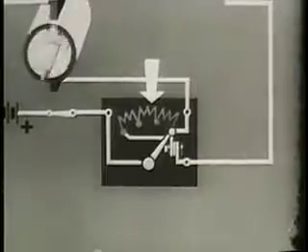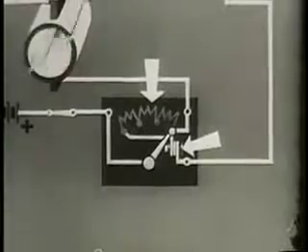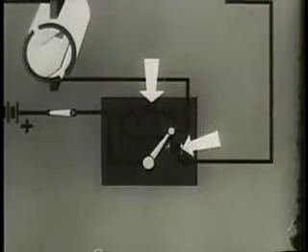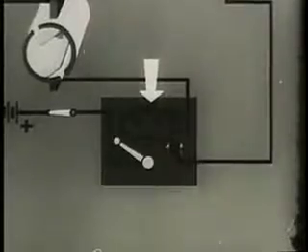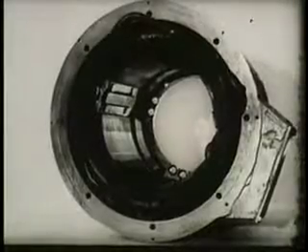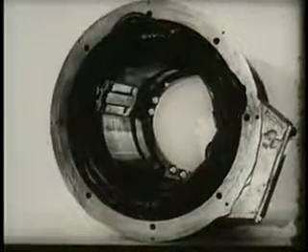The lever is held in the fully open position by an electromagnet. If for any reason the power should fail or the field coil open, the electromagnet becomes de-energized and the lever is returned to the starting position by spring action. Just as in DC generators, DC motors seldom use permanent magnets for the field. Instead, electromagnets are used. Like with a DC generator, field windings are constructed in several ways. Each type of winding has special characteristics, special values, and specific uses.